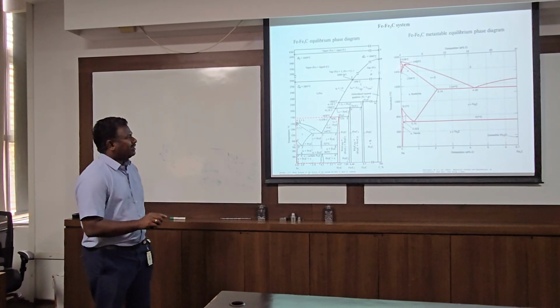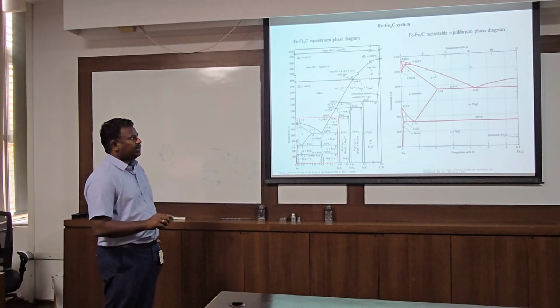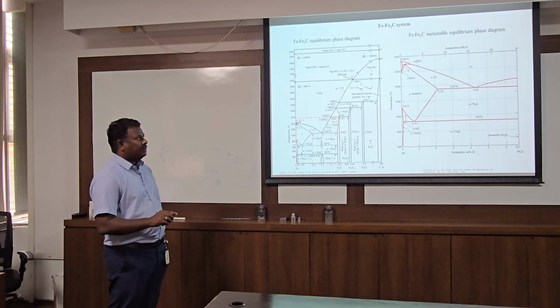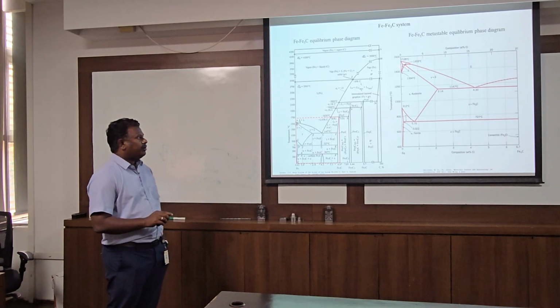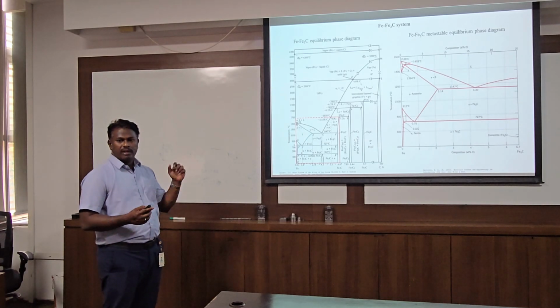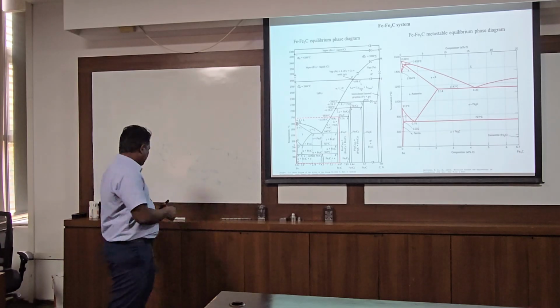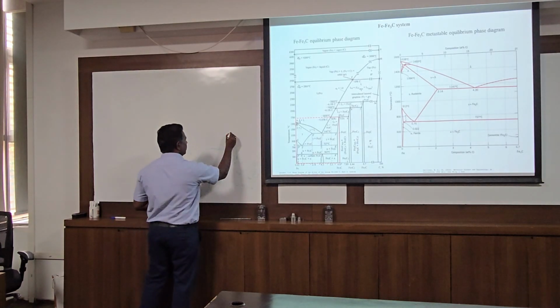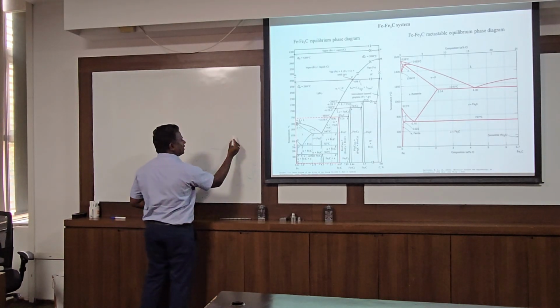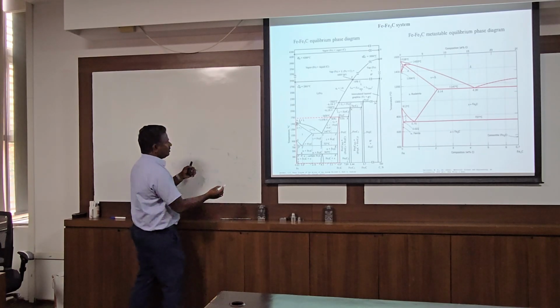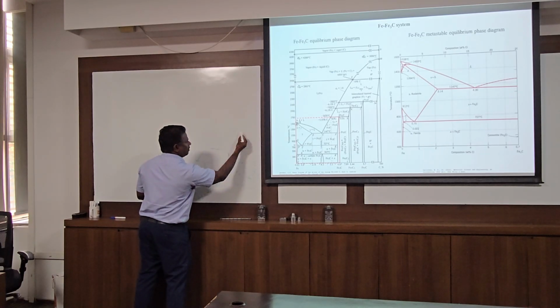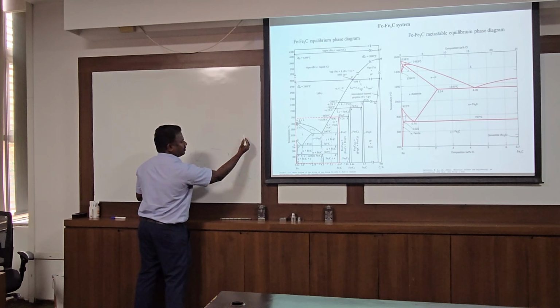This is a peritectic reaction. It happens at 1493 degrees centigrade. A peritectic involves one solid and one liquid together. Like, I have one solid, and in this system one solid is formed and surrounding liquid is there. Another solid will form as it solidifies. So this is solid 1, this is solid 2.